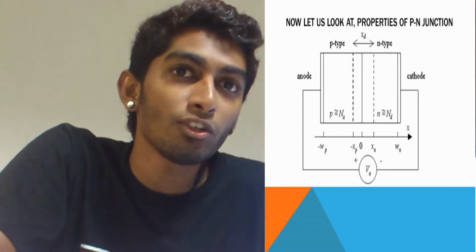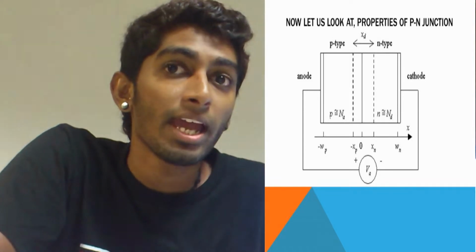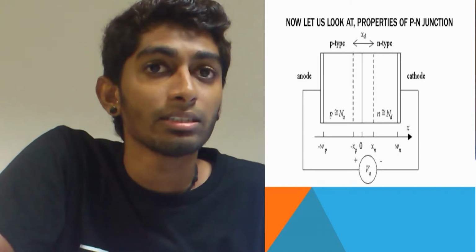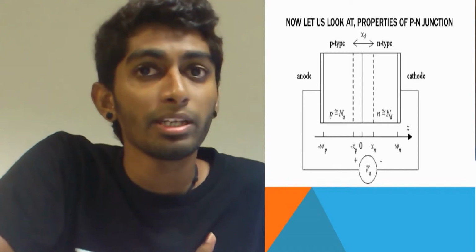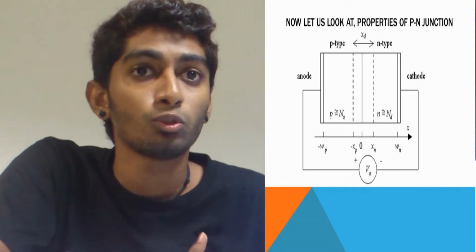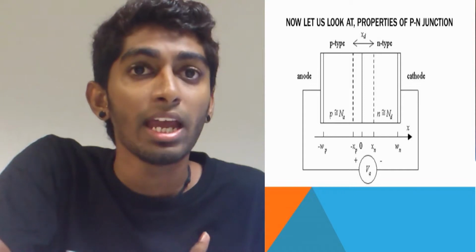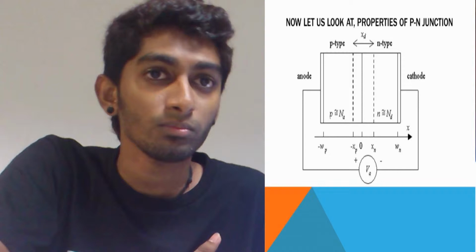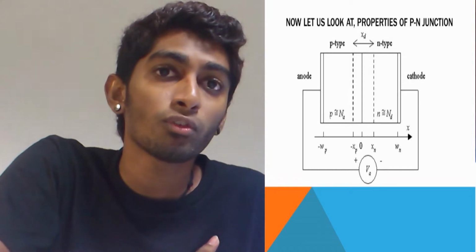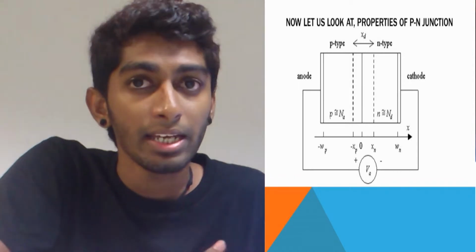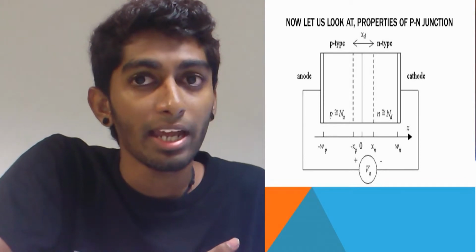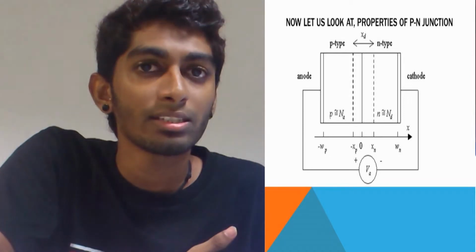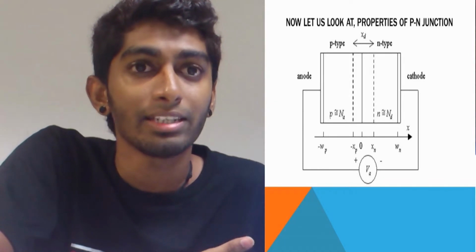A P-doped and N-doped semiconductor is conductive, and the junction between them can become depleted of charge carriers. Whether it is non-conductive depends on the relative voltages of the two semiconductor regions, and the non-conductive layer can be manipulated to work as a diode. The PN junction is one of the semiconductor electronic devices used in electronic applications such as diodes, transistors, solar cells, LEDs and integrated circuits.